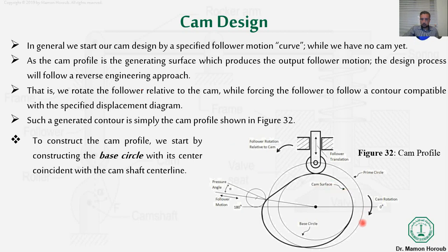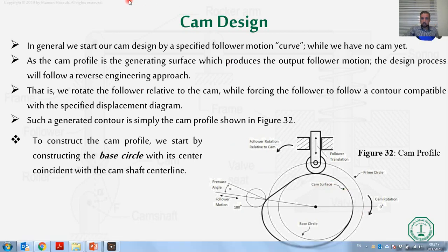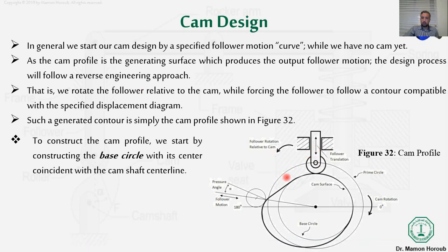As we see here in this example, this is the CAM profile, which is the dark black line, and here we have a roller follower. We will imagine this roller will move in this part, then this part, as well as this part, as drawn here, until we reach this point. And the touched points, or the tangent points, will give me the profile of the CAM.